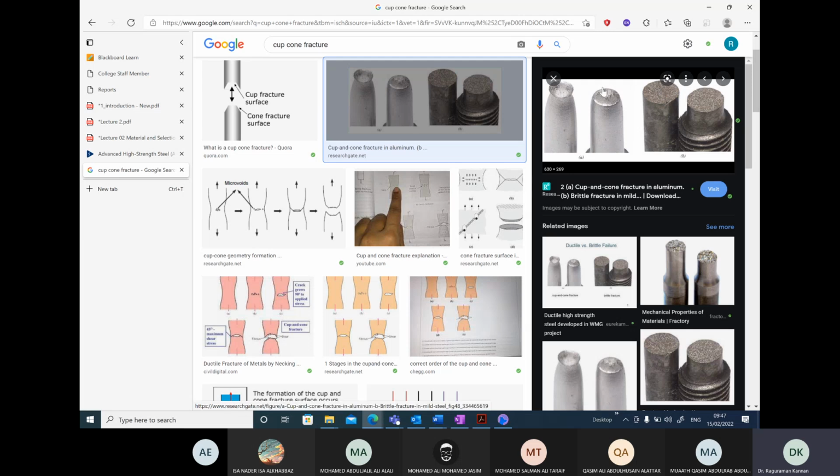If you recall from your solid mechanics course, you can argue based upon the Mohr circle that shear stresses are maximum at a 45-degree angle with respect to the principal stress direction. In the case of axial load, the principal stress direction is along the direction of the tensile load.